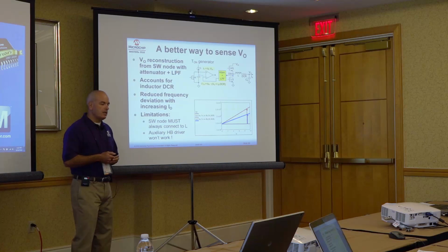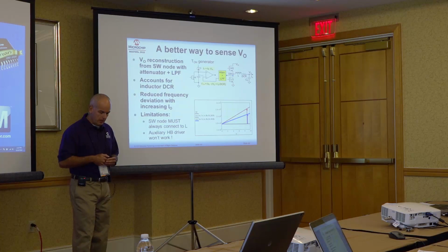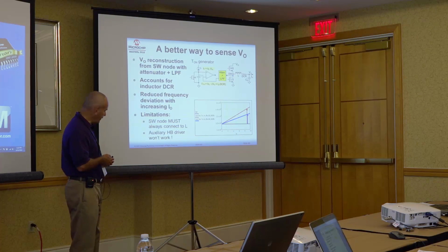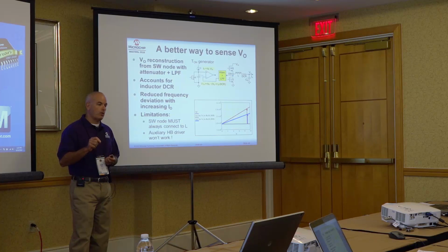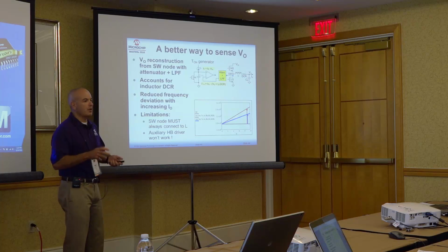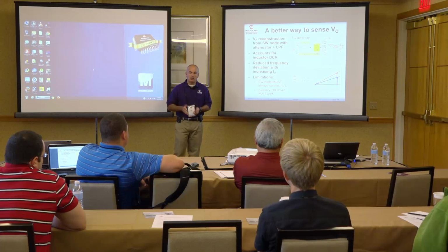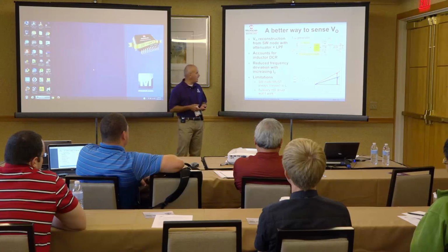Well, there is one limitation when you do that. On your IC controller side, you always have to connect the switch pin of your controller to the inductor. There could be one case where, for example, you want to put a half-bridge driver in between in order to drive beefier MOSFETs to crank up your power throughput capability.